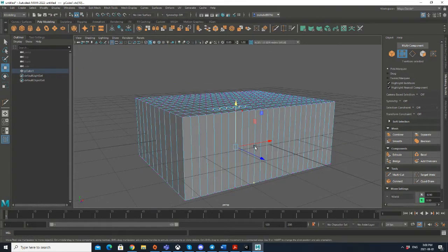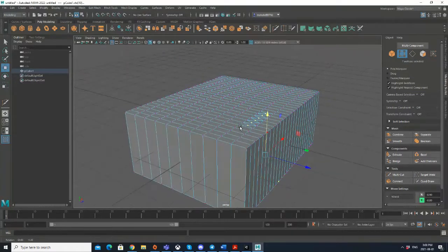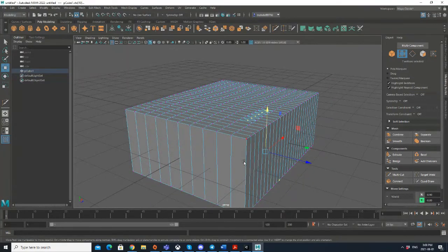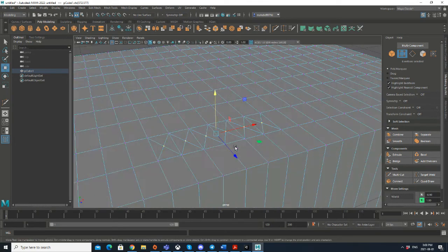You can see that the move tool goes into the center of these points, and by looking at this pivot I can say that I have selected one vertex which I didn't intend to. So by pressing Control, actually Windows, and going over the vertices you don't want, or clicking on them, you will deselect them.